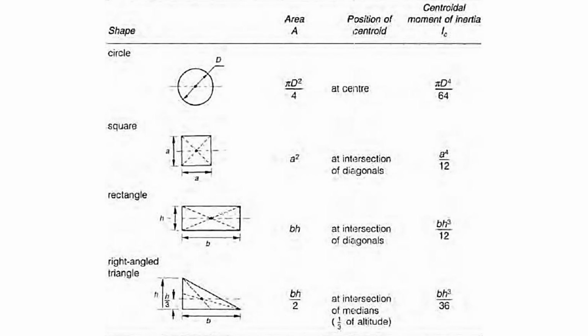Moments of inertia of plane areas. The moment of inertia, normally referred by the letter I, of a plane area, more appropriately called the second moment of inertia, is the sum of all elementary products of area elements and the square of each respective distance from the centroidal axis. For our purposes, the moment of inertia of a cross-section of a beam, combined with another dimension of that cross-section, is a measure of the resistance offered by the cross-section to the bending moment and can be related to the bending stresses induced in the beam by bending.